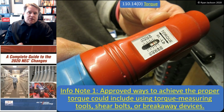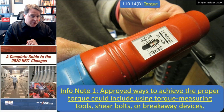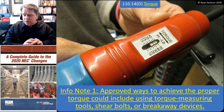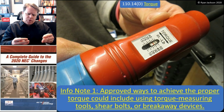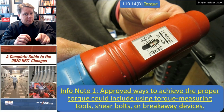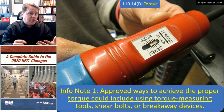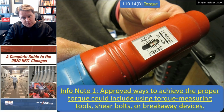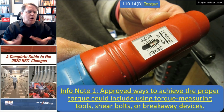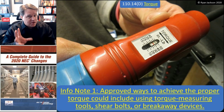Breakaway devices, like I talked about, are one method, but there are other methods as well. I'm led to believe that there's a busway product out now. I'm told that it's by Eaton, but I haven't seen it, so I want to be clear. But there's a busway product where when you bolt the busway together and crank it down to the appropriate tightness, the bolt head actually will change color, like from red to green or green to red, letting you know that you've achieved the proper tightness. So measuring things with a measuring device is not always appropriate. We just need to make sure that we're tightening things to their specified torque.